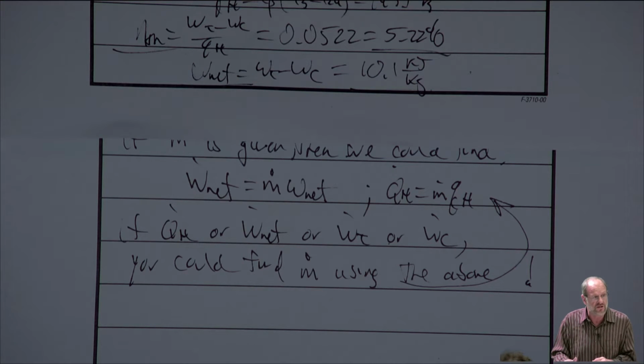So we can get those other properties either through equations like the ideal gas equation of state, or through tables like the property tables for refrigerant 134A or water that are in your book, or even using graphs we can find relationships between properties, for instance the compressibility chart. But nonetheless, we were able to understand that property data exists in various forms.